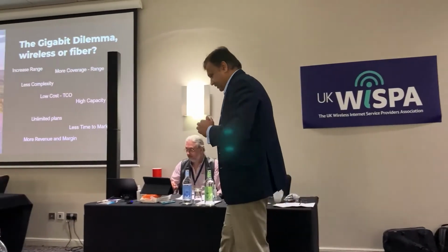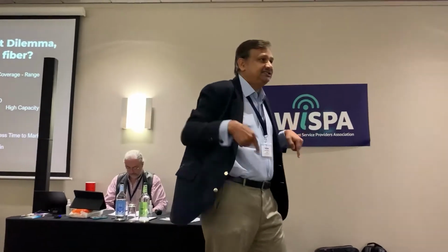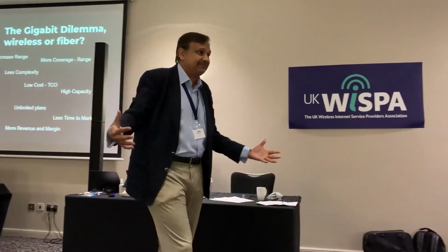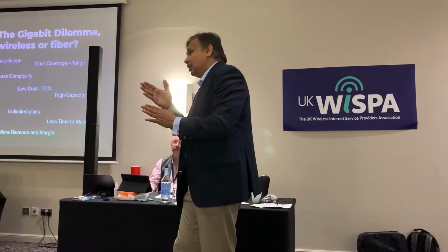Okay, what is the other option? Use normal wireless, LTE and 5G. A lot of buzzwords are coming up. Now, a typical LTE site, 360-degree, I have been designing antennas for LTE for many years. 120-degree sectors, 3 sectors, power consumption per site about 10 kilowatts. Data rate at 2 kilometers, 3 kilometers, 900 megabit per second. LTE is not good. Go to 5G. Okay, with 5G, I can have 2 gigabit per second maybe. How much distance? 2 kilometers, 3 kilometers. What is the power consumption? Right? So it is good, but it has its own limitations, because I want high capacity and also good ranges.